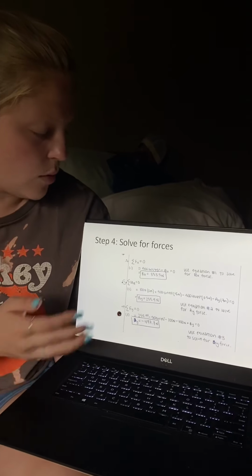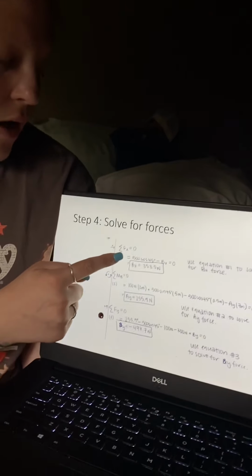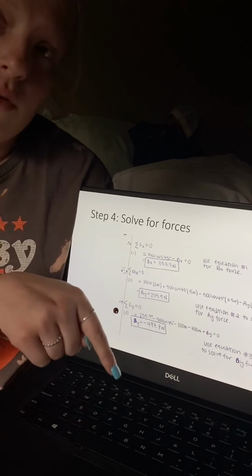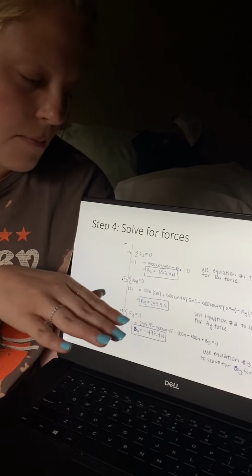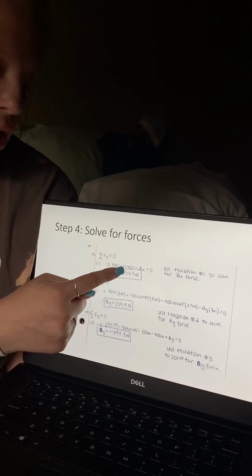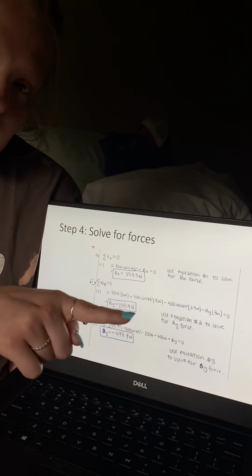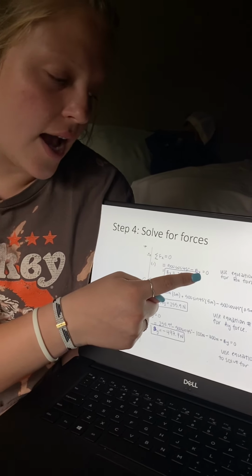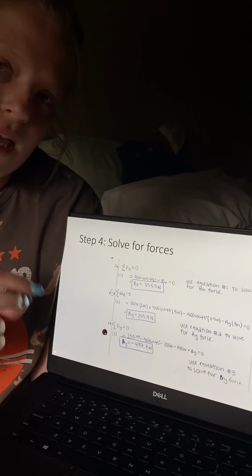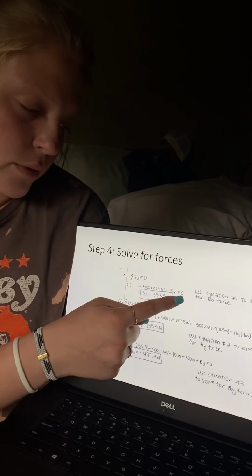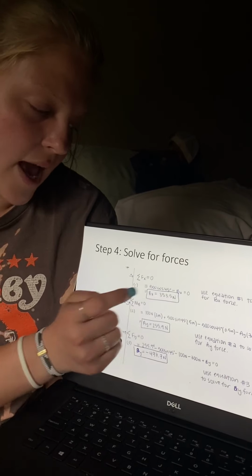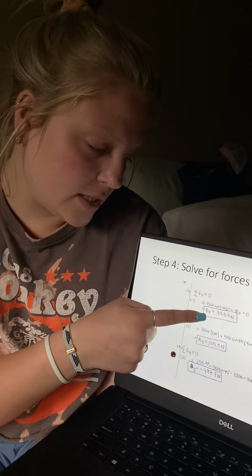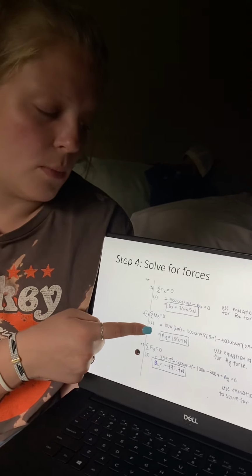And so how I did this was I took the sum of the forces in the X direction equals 0, and I plugged in that downwards and diagonal X force, which was 500 cosine 45 degrees, and that was in the positive direction to the right. And then I subtracted the X component of that B pin, and those are both equal to 0. So as you can see, you can easily solve for BX here, which I got to be 353.5 newtons. And then using this, we can go down and solve for the moments at B.